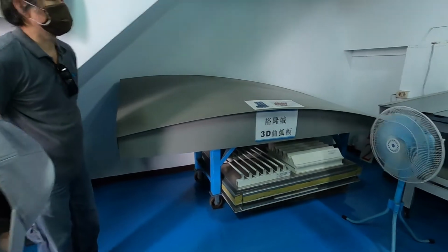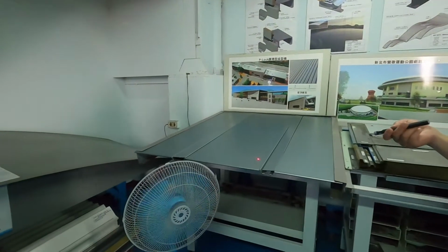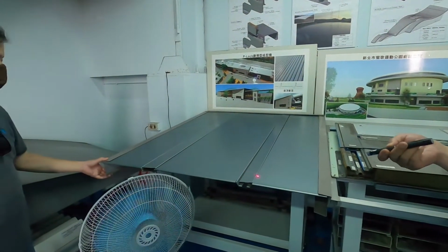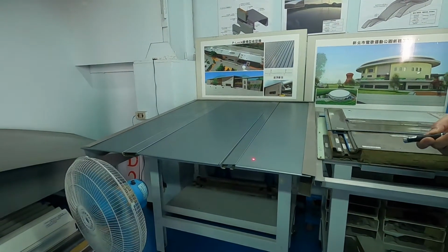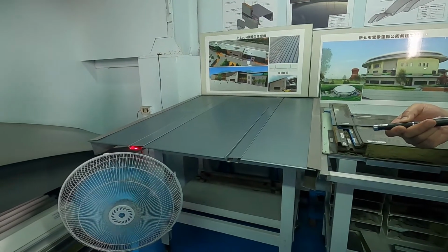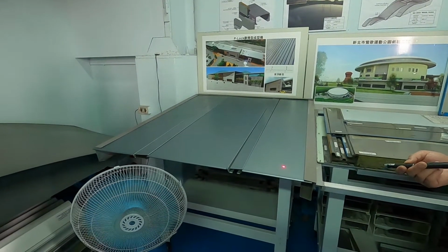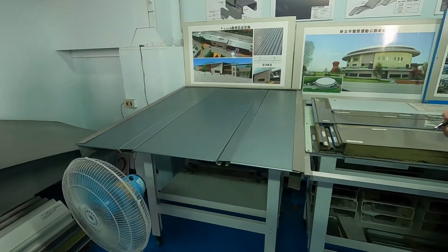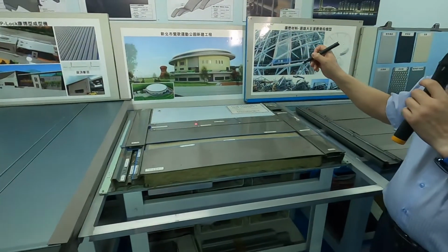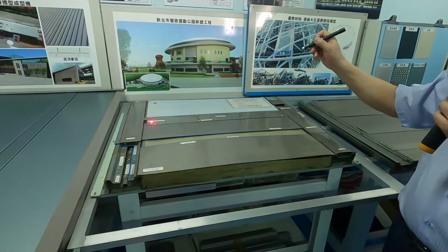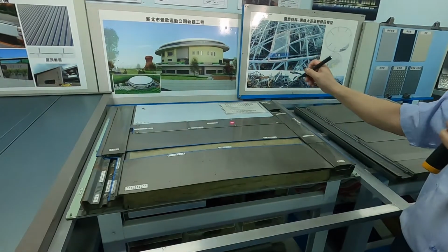So then take a look at the small model like this, which is a composite roll form roofing system like in Taipei. This is the one that we use with different widths from panel to panel. So you know all my secrets. And between the lower panel and the upper panel, we create a butt joint gap here with a membrane system and put on an extra strip to cover the panel.